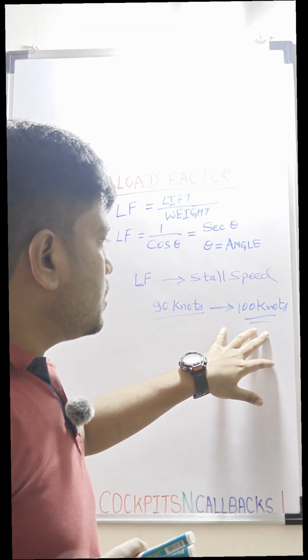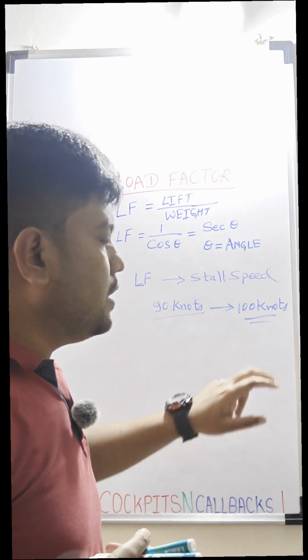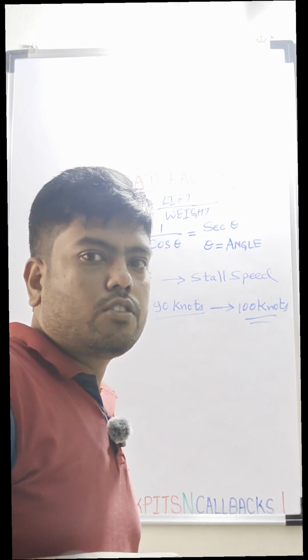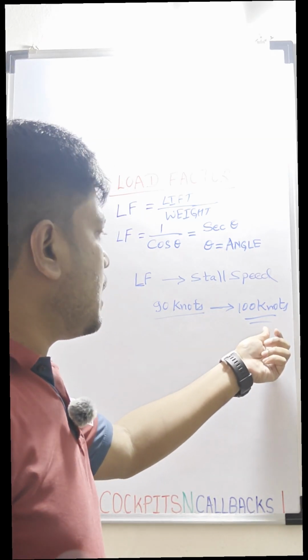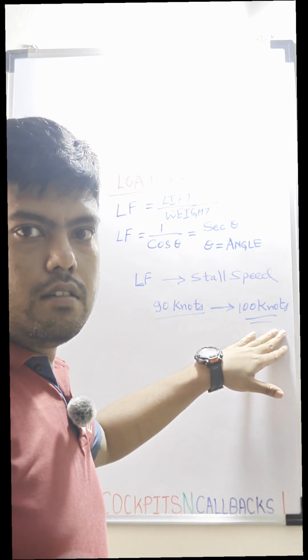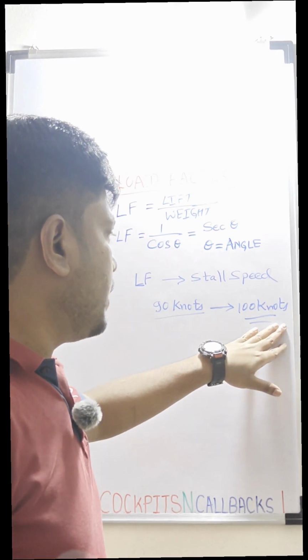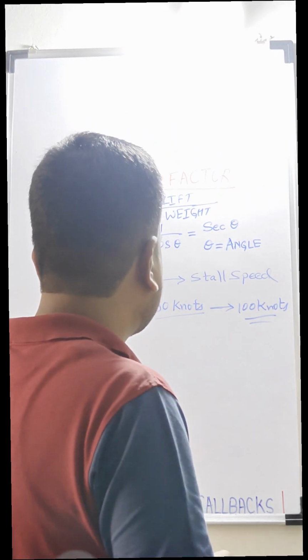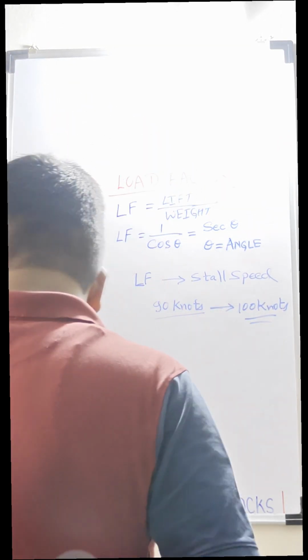And why is it important to understand? Because if the stall speed increases, even if you are actually having a higher speed, there are chances that you will hit this number very easily, right? The increased stall speed for that aircraft, you are going to hit that very easily, and then eventually you are going to lose lift, right? So that is how it becomes really important.